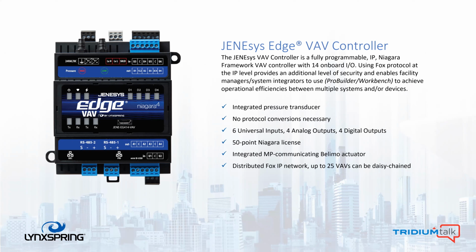The VAV controller also comes available with different tool sets: configuration tool sets, commissioning tool sets, and balancing tool sets. So you could, but you don't have to, operate purely within a Niagara experience. Even though it's all Niagara, same Niagara that's on the 534 is on the Edge VAV, right? Except we've put the VAV application. But using these tools that we've developed, you can quickly commission, balance, and integrate many of these Edge VAVs, including Edge 414s, in an application using the Niagara framework. Okay, let's move on to the next slide, please.